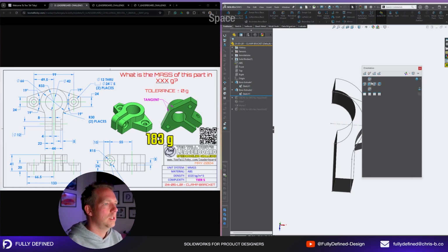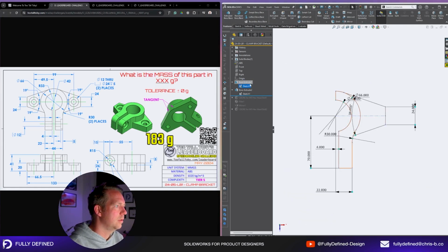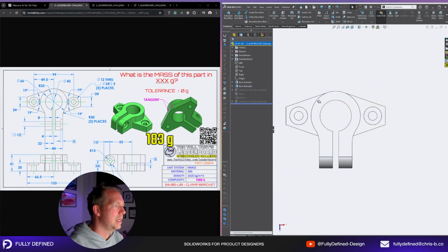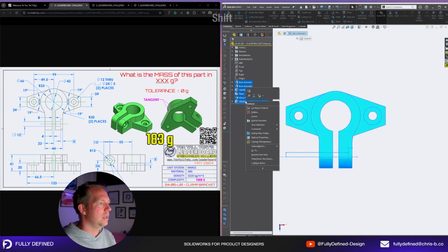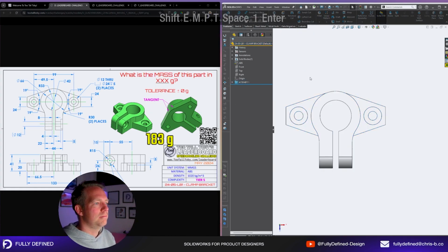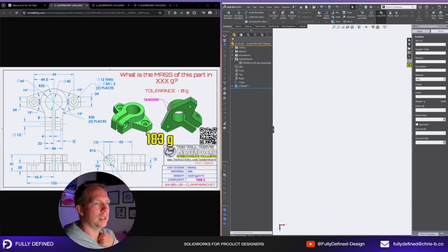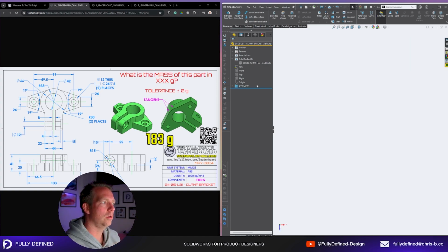And I'm thinking it's something to do with this shape here. So what I'd like to do, given we already have the references and what I did last month, I just put all this in a folder. Just name it, attempt 1, hide that body. When you hide that body, it actually takes weight out of your model. So you can have multiple attempts in one model as you're working.